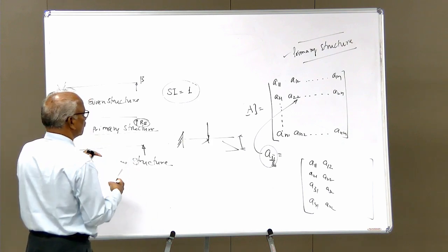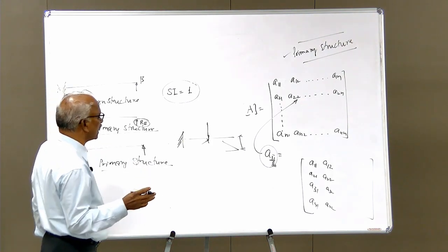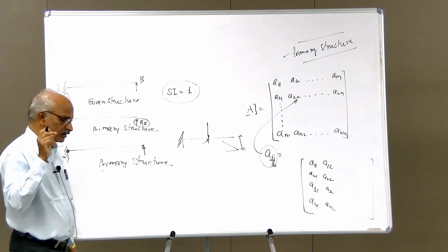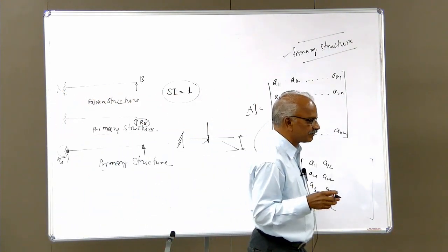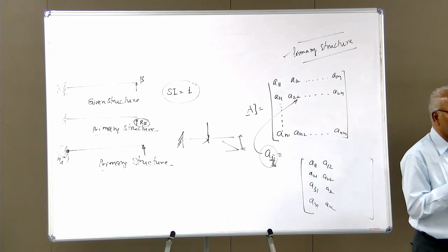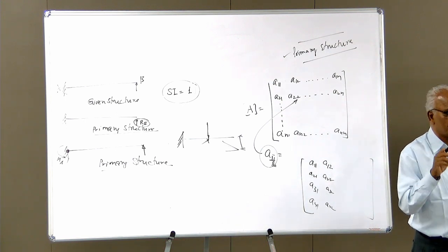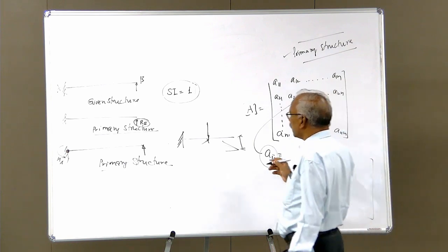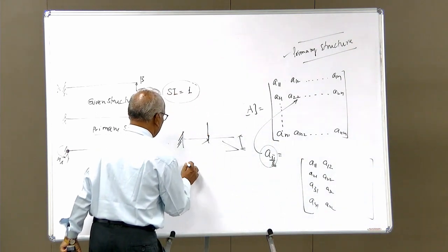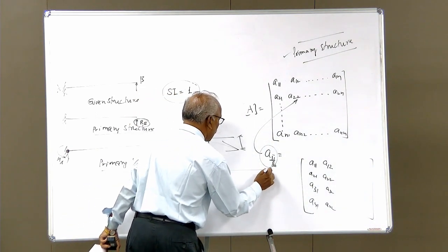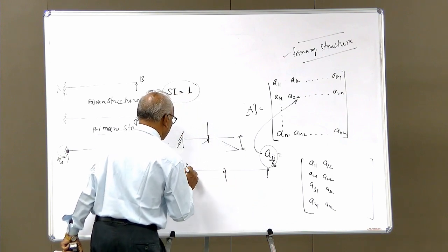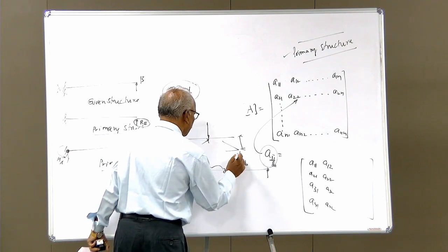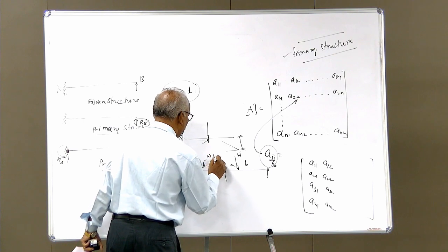Also, in the analysis, suppose you want to analyze a continuous beam, you must know something about the fixed end moments. In the 4th semester, you have studied fixed beams and continuous beams. So, finding out the fixed end moment for the given span and loading is a full problem in your strength of materials 2. Now it becomes a fundamental. Suppose you are asked to analyze a continuous beam. You are given a UDL over the entire span AB and a non-central load on BC. This is W per meter run.